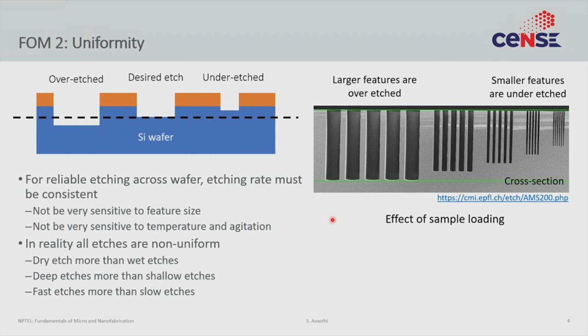It is possible that the etching solution itself has fundamental issues which prevent it from being uniform. A good example would be if an etching solution is not very ideal and tends to produce precipitates. The precipitate would form randomly on different parts of the wafer, and different parts of the wafer would then be exposed to the etching solution at a different rate, which might lead to a difference in etching.